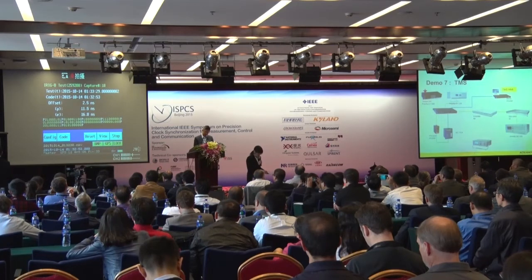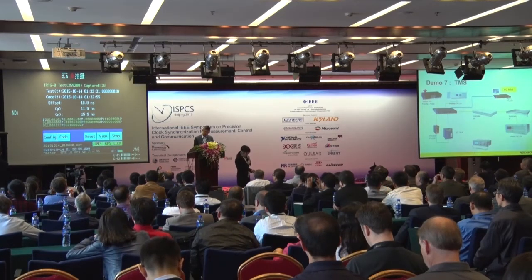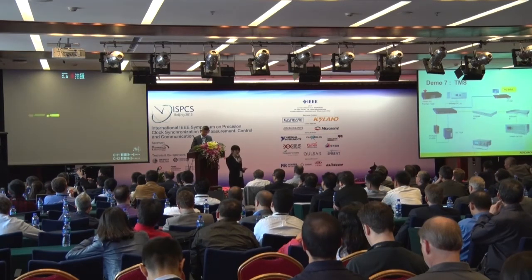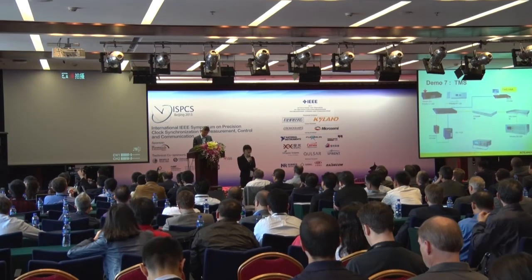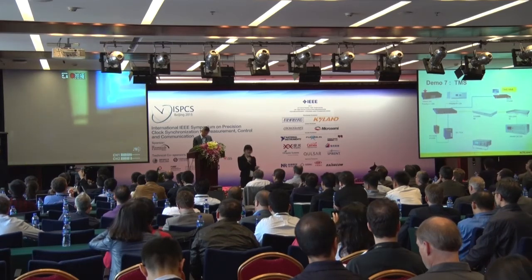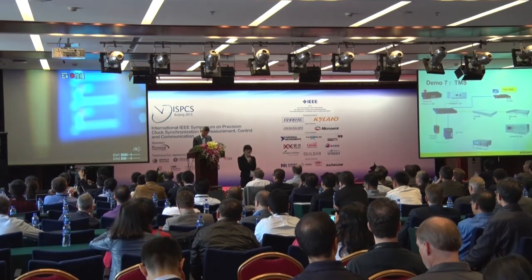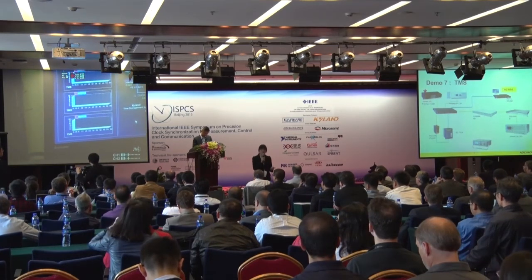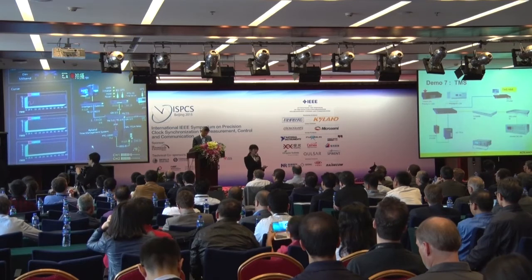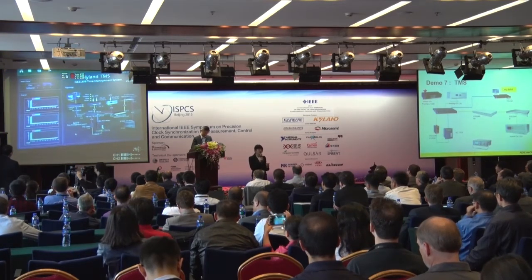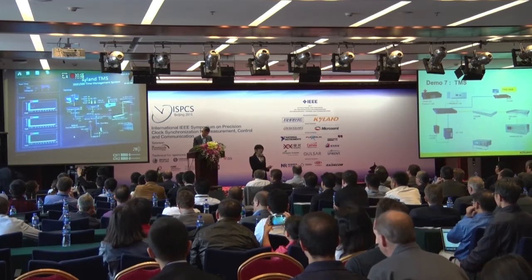Now on to TMS. Since we know that for time synchronization via network, it is very difficult to tell how the end device is really synced with the grandmaster or not. Sometimes we use SNMP or MMS reports to get self-report information from the end devices. But this kind of information is usually based on predictable events.